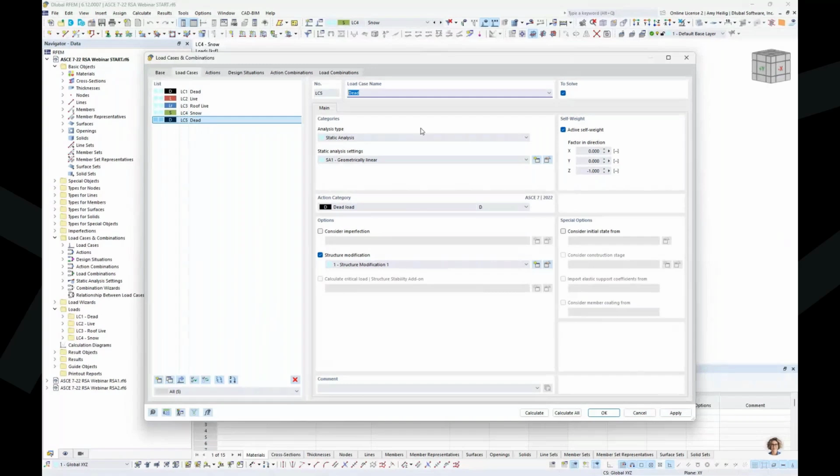And I'm not quite yet ready to jump into the response spectrum analysis, but I am going to apply the seismic loads as a static load type to begin with. So therefore, we can rename this one to vertical seismic. And I also want to specify here directly from the code, section 12.4.2.2, and in particular equation 12.4-4A, exactly the equation that I will be applying for this load type. So referencing this equation from the code, this will be a factor of 0.2 multiplied by SDS, multiplied further by our dead load. Now, again, the advantage here is that we are just going to apply a static analysis.